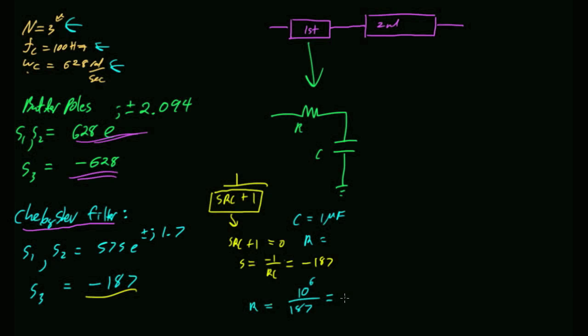Okay, so this is about 5.3 kiloohms. My calculator actually says 5.3476. Am I going to write all those numbers down? No! Good luck going to the resistor bin and finding a resistor with value 5.3476. Remember, resistors always come with plus or minus 10% anyway, or 5% or whatever. So don't try to impress me with 8 decimal places here. It's meaningless.